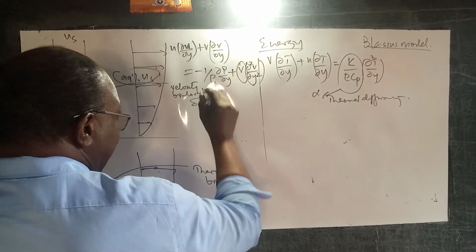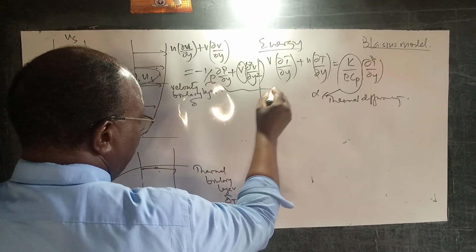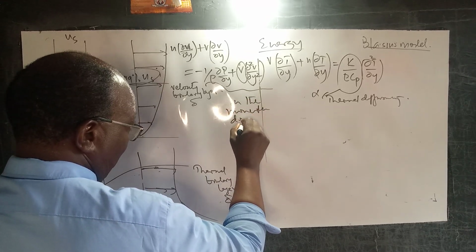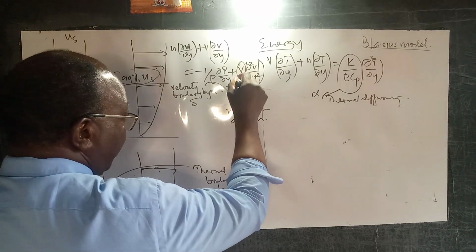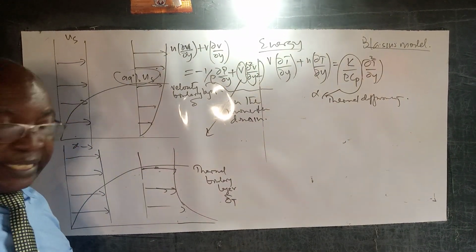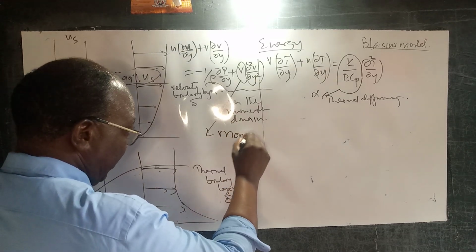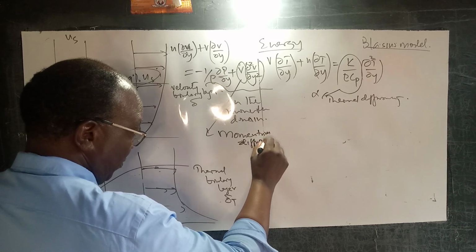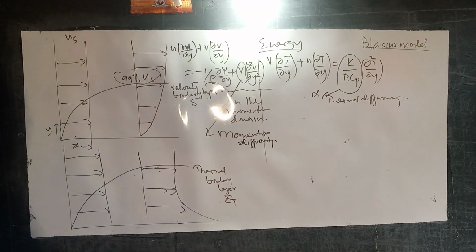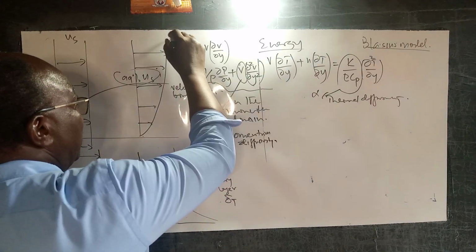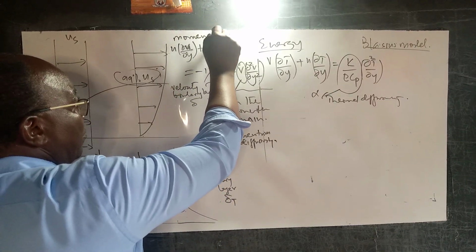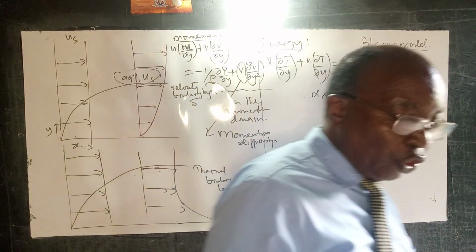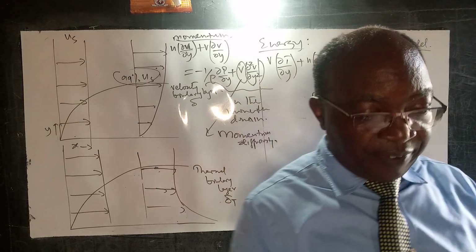So in the momentum domain, we can think of this V, which is kinematic viscosity, as momentum diffusivity. So we have now, let's call that momentum balance, energy balance. Then we now want to look at concentration or mass transfer or mass balance.